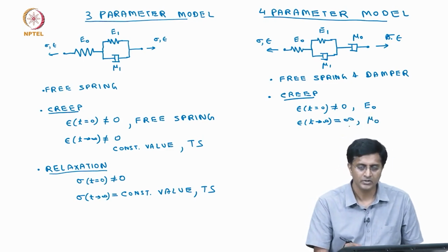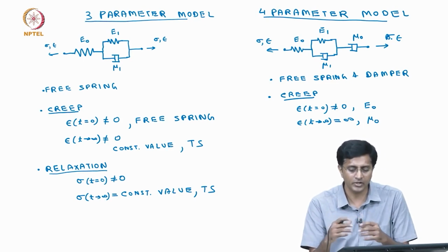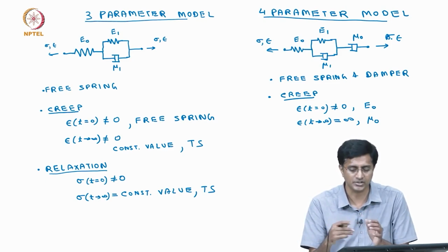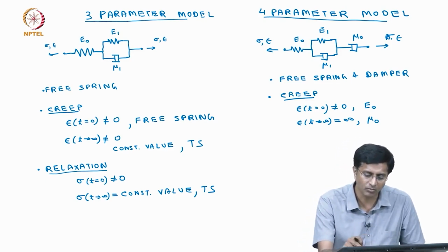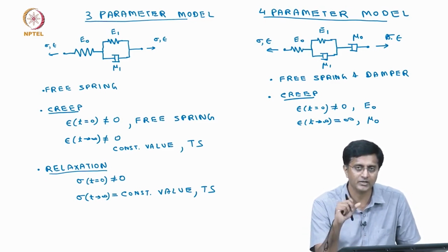Okay. So, initially there will be some nonlinear behavior, meaning the relation between strain and time, not the stress strain. That is because of this Kelvin model being here, or this E1 and nu1 which are parallel to each other.